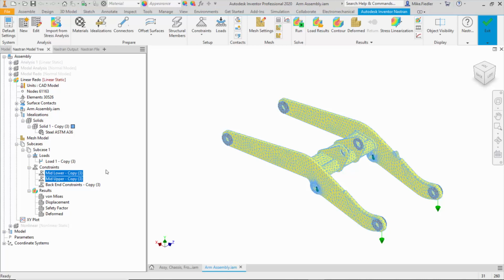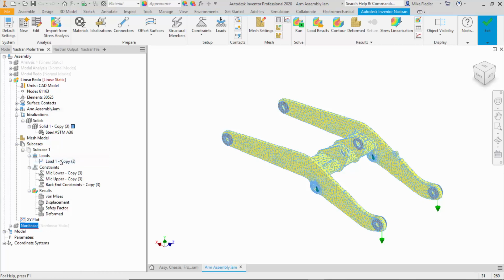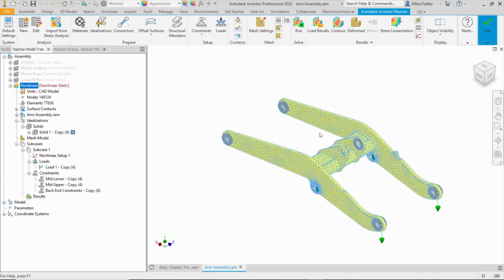incrementally, if you will. So right-click on that analysis, and we do a duplicate here. Let me move into that analysis, activate that one. And so I wanted something interesting to happen with this analysis. And we saw from the results of that linear analysis that our results were somewhere around the 6,000 mark, between 6 and 7,000. So if we expand the material here,